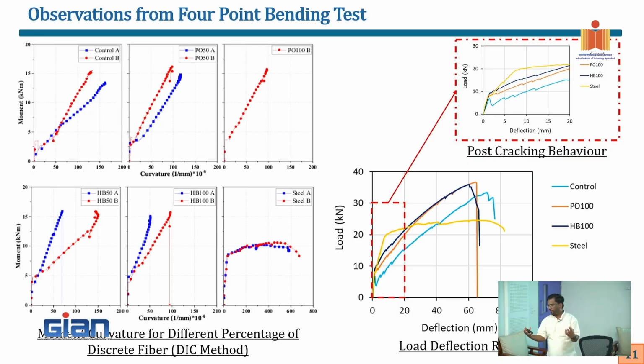Steel plus synthetic. Now I told you steel fibers are quite effective in arresting the crack. So I get both, right? So if I do that, the dark blue color curve goes very close to that of steel. That's the whole idea, right? So the serviceability performance now will become comparable. Even if I put the same rebar, a 10 mm bar in steel, I get a 10 mm bar in GFRP. But in addition to that, I also need to put some discrete fibers. Again, the cost is going to go up.